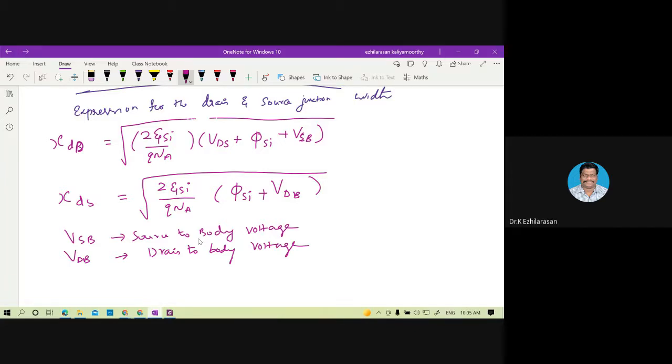Now as the source and the drain get closer because of the short channel, they will become electrostatically coupled. If it is electrostatically coupled, then the drain bias can affect the potential barrier to carrier flow at the source junction. As a result, the sub-threshold current increases.